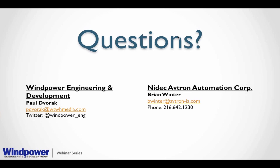That's a good question. Depends on the model. I know that's a weaselly answer, but you have to go back to the manufacturer. You have to go back to Avtron and give them a part number and say, this is the 56 I've got. This is the AV that I'm replacing it with. Are these interchangeable? You need to exactly check the part number. It's not a good general statement. So I'll say partially false.